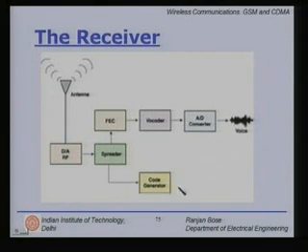Of course, you need to have a code generator in order to despread. Which code is being used is pre-decided during the conversation. If I go from one base station to another, then this code generator will switch from code 1 to code 2.